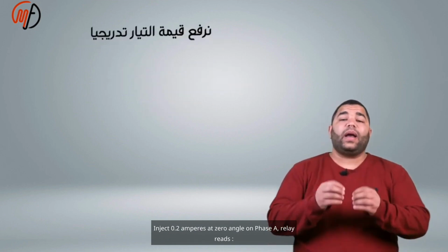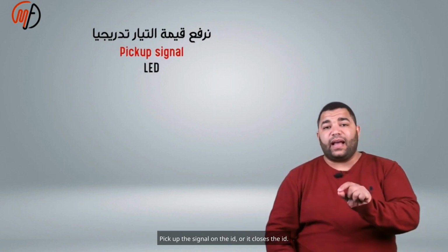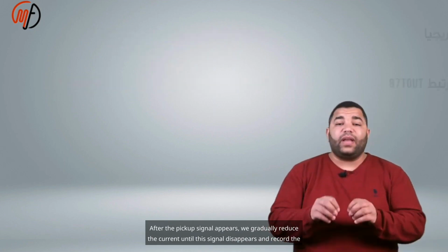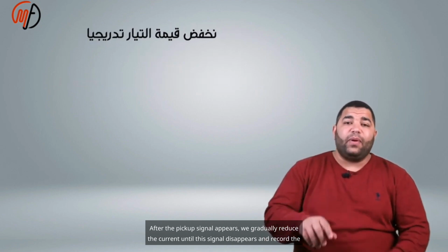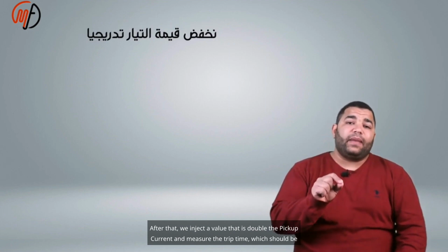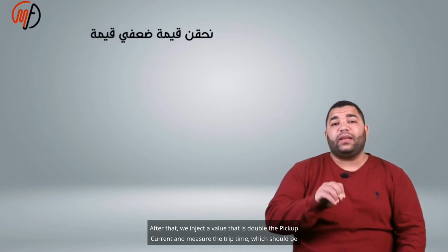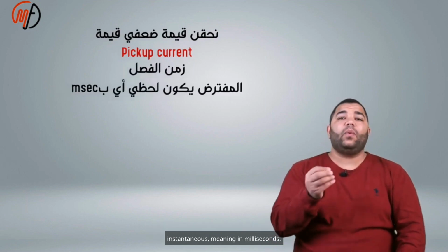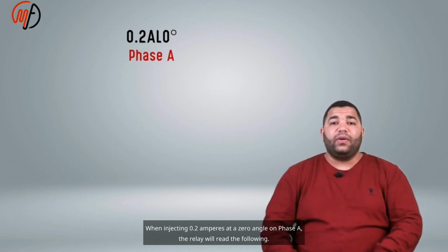Inject 0.2 amperes at 0 angle on phase A. The relay will read the pickup signal on the ID, or it closes the ID. After the pickup signal appears, we gradually reduce the current until this signal disappears and record the drop-off current value. After that, we inject a value that is double the pickup current and measure the trip time, which should be instantaneous, meaning in milliseconds.